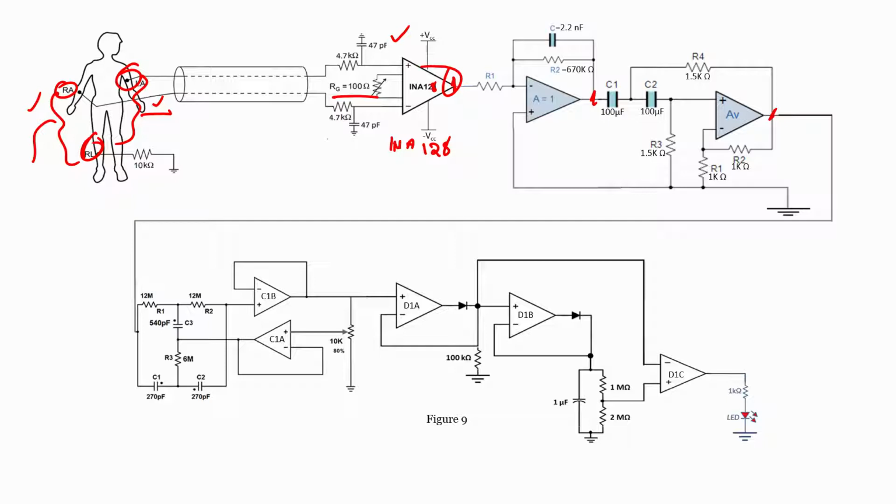If you recall, baseline wandering is nothing but the signal always wandering with respect to this baseline. This is because of respiration. During the respiration of our breath, it creates some kind of noise in the system, which will be somewhere around lesser than 0.5 Hz. Since we are using a high pass filter, after passing through the high pass filter we can see the complete removal of our baseline wandering, and even motion artifacts, which are in the same range, will be completely eliminated when we pass through this particular system.